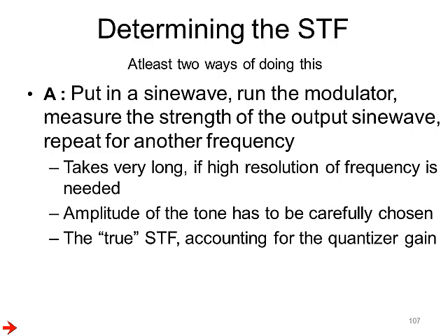Further, the amplitude of this tone has to be carefully chosen because if you choose the amplitude to be too small, the sinusoid could be swamped by shaped quantization noise. If it is too large, you will make the modulator unstable.